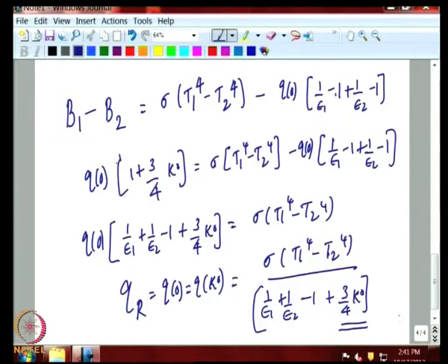For example, if you look at the insulation used commonly made of aluminized mylar reflective layers, hundreds of them, the emissivity of these surfaces may be 0.01. You can see that this will add up to around 200. So, unless the radiation optical depth of the gases between the reflecting layers is very large, this term is not important.